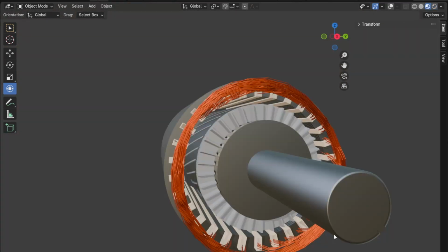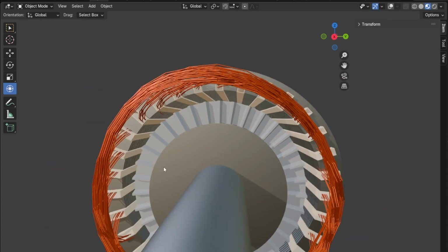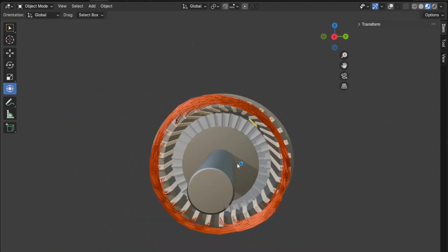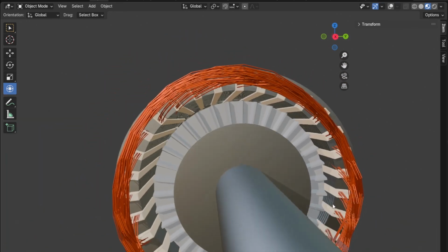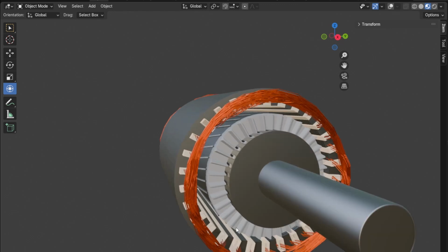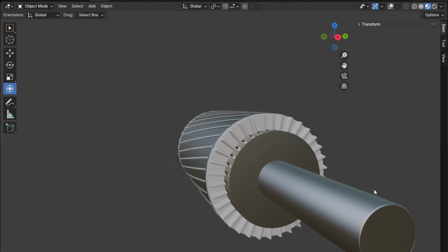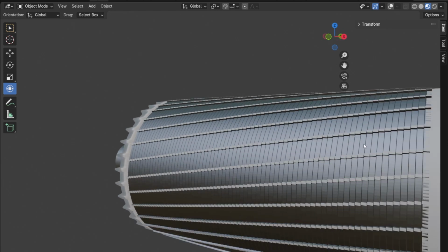All right, so here is the rotor and the stator, and I took away the pretty background because it was messing with the rendering a little bit. But you can see there's this small air gap between the two. And the rotor is suspended by bearings on each side, so it sits constantly in the very center of this stator. And that is critical to a good motor design. You don't want it off-center because you'll get wobble, so they take great care to make sure that the bearings are centered properly on these. So let's take this stator away and we'll just look at the rotor itself. Once again, it's laminated for the same reason.